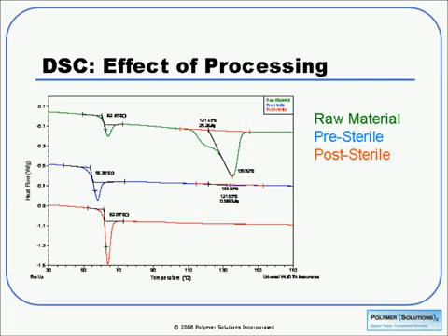Now, if we do a second heat of this sample, we will have normalized the thermal history, erased everything previous, and that may be useful to determine if you have differences in lots of material, because that second heat is just indicative of the material itself.